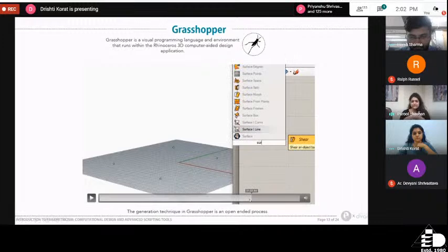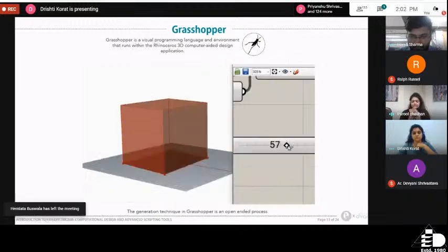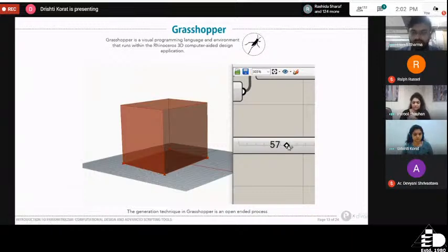When we talk about generative design, this slider, for example, if we're talking about a structure, let's assume we're talking about the diameter of a structure. So this slider would be an input for the diameter. If you're using a generative plugin, it gives you the leverage that it will automatically connect to this slider and give you an optimum result.